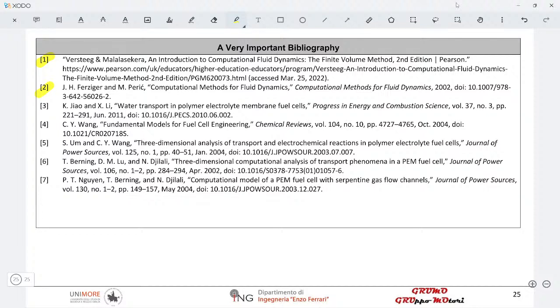So yes, you can in principle apply this same set of equations to any number of individual cells, and it would describe the behavior and the different hydration states of each cell in the stack. But from a practical point of view, this is not affordable most of the time.